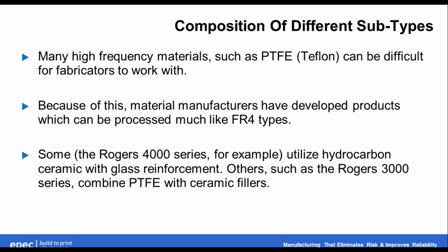Some of these materials, like the Rogers 4000, utilize hydrocarbon ceramic with glass reinforcement, and others, such as the Rogers 3000 series, combine Teflon with ceramic fillers, and we'll get into why that is in a minute.